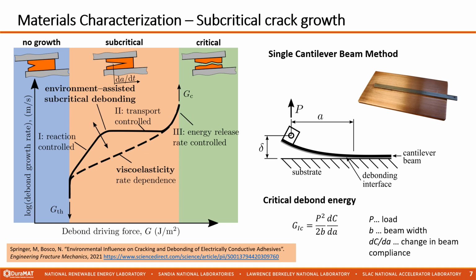In between, we have a region of subcritical crack growth, which can be caused by a variety of different mechanisms, as for example, environmentally assisted cracking or the material behavior itself, like viscoelasticity. Since we expect our modules to be in the field for a long time, we certainly don't want to have debond driving forces within the critical nor subcritical regime.